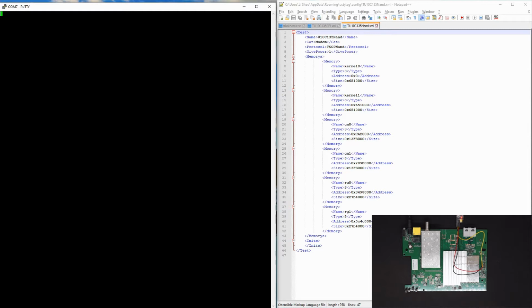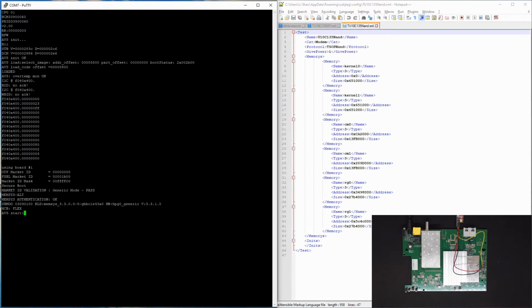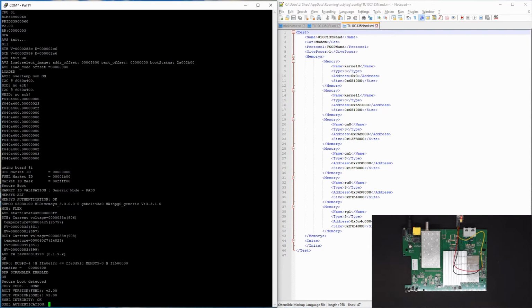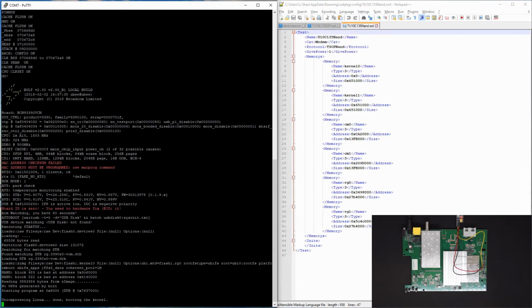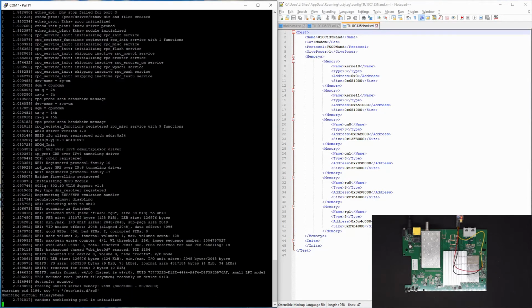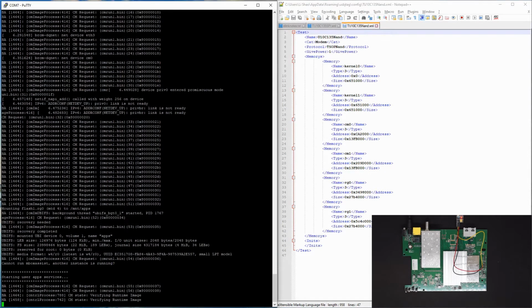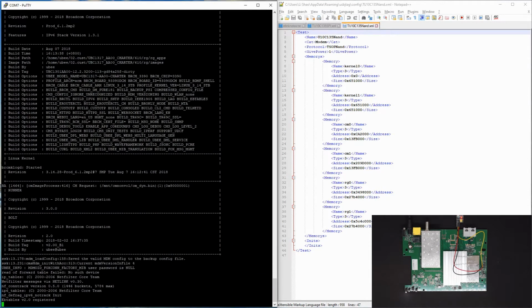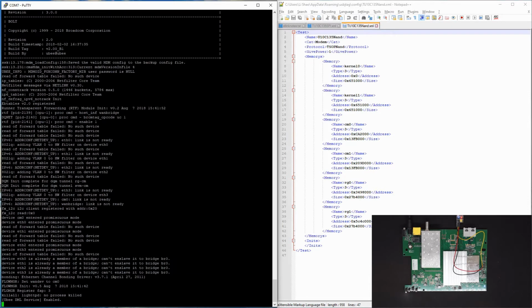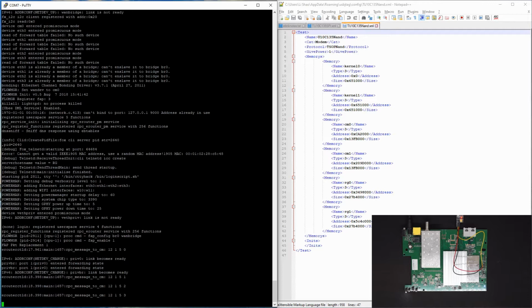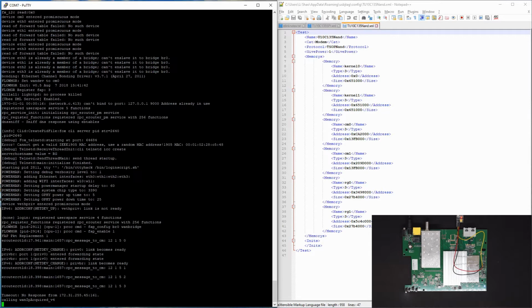Then I'm going to power on the modem. It will start printing out information. So let's wait for it to stabilize. By the way, other people might find more information from this log. My purpose is to find the layout of the flash from this log. Okay, I'm going to power off here so it will not scroll anymore.